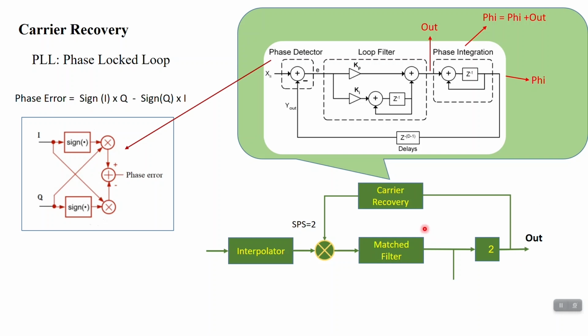and here is the carrier recovery structure in detail. You can see here phase error. The first step is estimation of phase error. For estimation of phase error, you use the final sample, in fact, and the phase detector is used to detect the symbol phase error compared to the reference symbol.